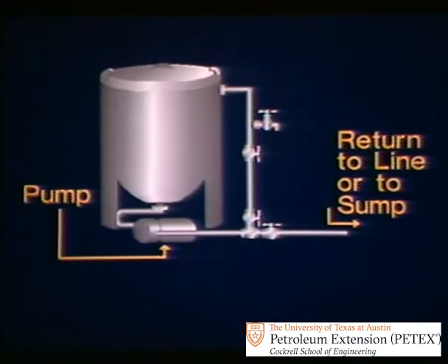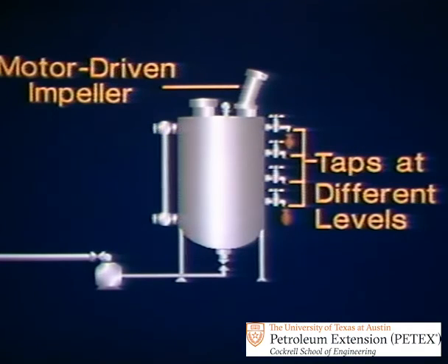With suitable valves, the circulating pump can also be used to pump excess sample back to the pipeline or to a sump after the portion needed for testing is drawn off. A less desirable way to mix the sample in the receiver is to use a motor-driven impeller. Taps located at different levels must be used to draw off samples into centrifuge tubes to determine proper mixing.